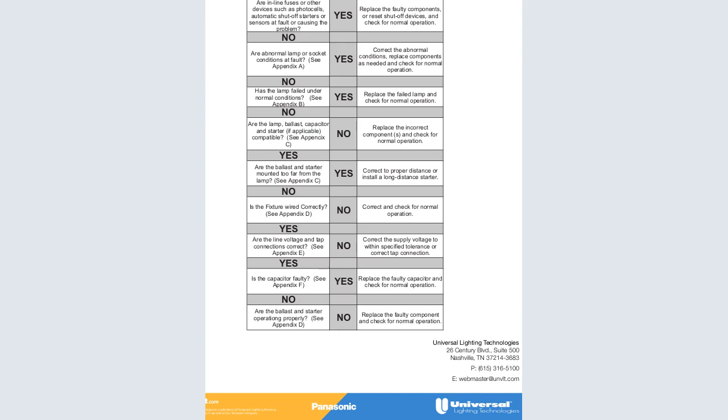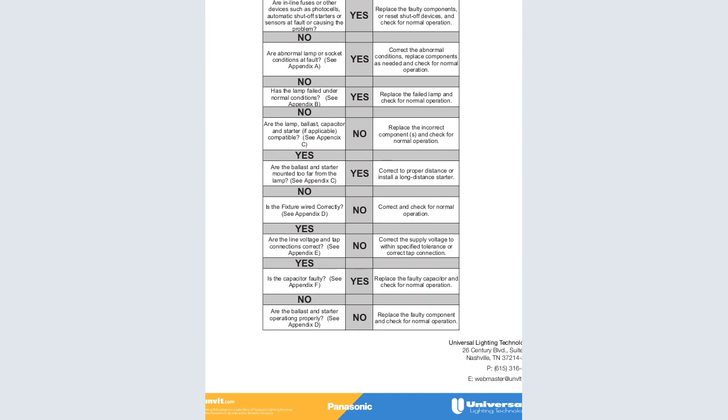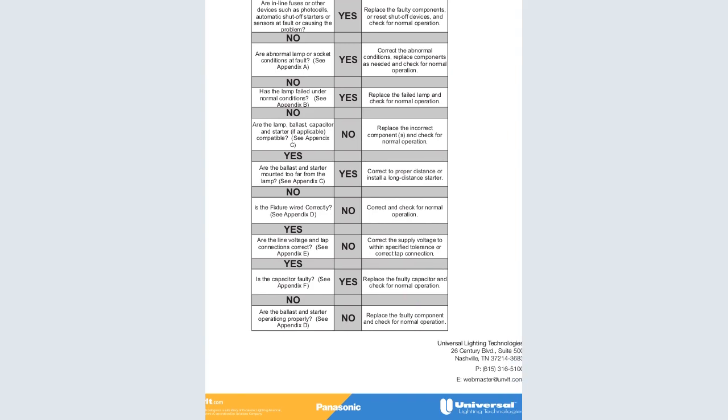If the answer is yes, then is the capacitor faulty? If the answer is yes, then replace the faulty capacitor and check for normal operation. If the answer is no, then are the ballast and starter operating properly? If the answer is no, then replace the faulty component and check for normal operation.